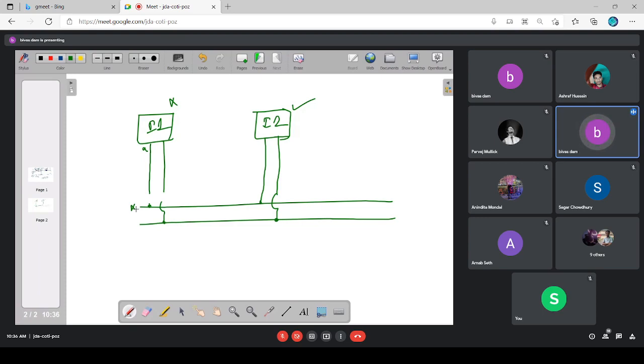So the output gets electrically isolated from the external world. Otherwise, this output will have only logic 0 and logic 1 states. Only when this output device needs to be disabled from the external world should it place infinite impedance to the external world. Is it clear now?